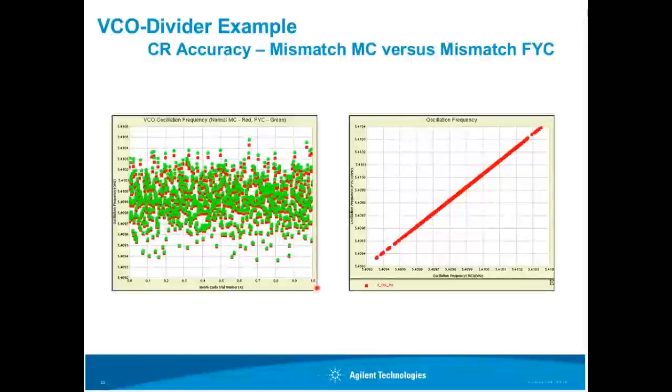You could take a normal state where you look at the nominal performance metrics for your design, enable the Monte Carlo analysis with fast yield contributor and mismatch, and it'll automatically pick all those up. You don't have to do anything special there. But you do have to set them ahead of time. So the answer is yes, but you do have to do that up front.